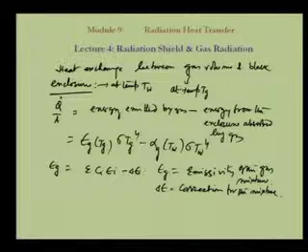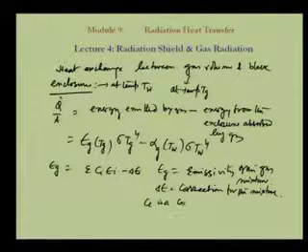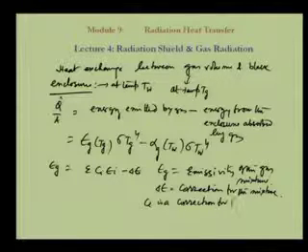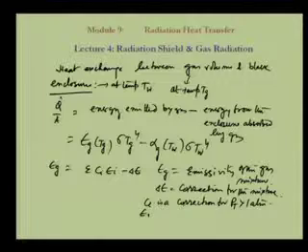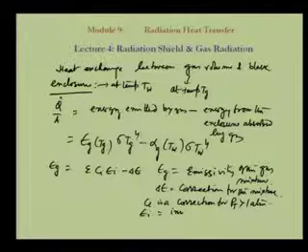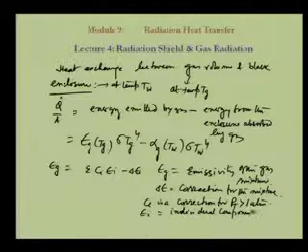That means it is the individual emissivities minus the correction term. C I is a correction for total pressure greater than 1 atmosphere, and epsilon I is the individual component emissivity.